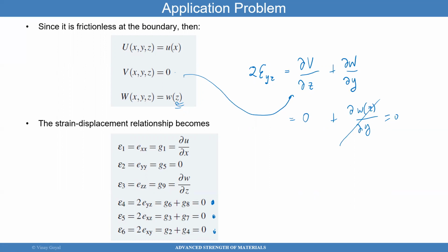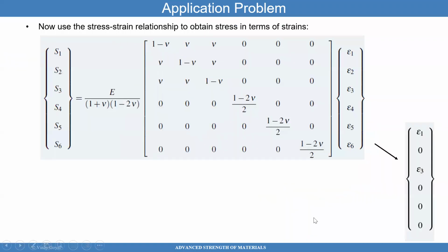This is just a strict definition. We used the fact that epsilon xx equals partial u with respect to x, and I'm using this quantity here, so that becomes partial small u with respect to x. All I've done is use the strain deflection relationships to get there. And then I can use the constitutive law. We know the stress field, and this doesn't have to be memorized.